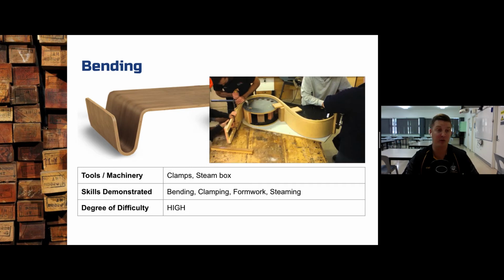That's important for you to understand how bending works, because when you have a tree at home that's still alive and you grab a branch and you pull it, if that branch is still living, the branch will spring, bend and bounce because it's filled with moisture and the fibres in it are able to bend. However, when a tree has been seasoned and that moisture's been taken out, the fibres have stiffened, and so instead of bending like they do when they're green, they will literally just snap and break.